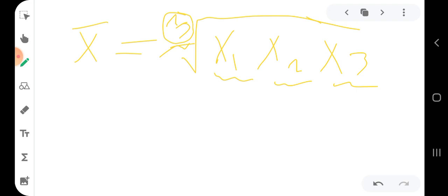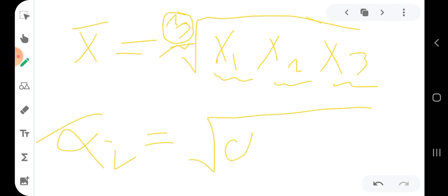And this is what you are going to use if we would like to average this alpha. So you can average the relative volatility of any component. For example, if you have the relative volatility of this component at the feed, at the distillate, and at the waste, you multiply them and then take the cubic root. It has an index of 3.